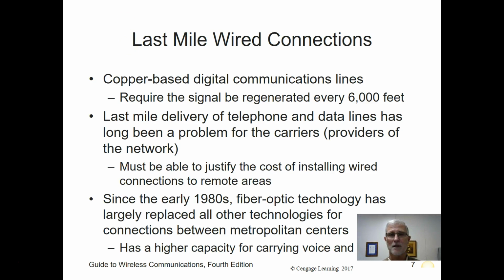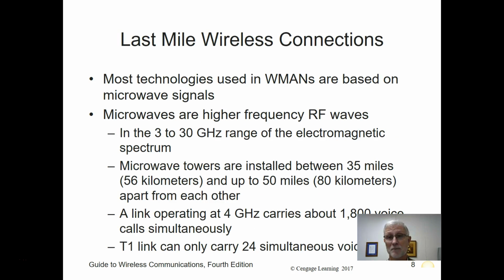Now, if it's copper based, like DSL, the signal has to be regenerated every 6,000 feet. So I have to put a repeater or some device in to regenerate the signal about every 6,000 feet, so about a mile. It varies based on who your telephone company is, what your ISPs are, and how much cost you're willing to spend. But just know that since 1980 or so, fiber has been trying to replace as many of those as possible.